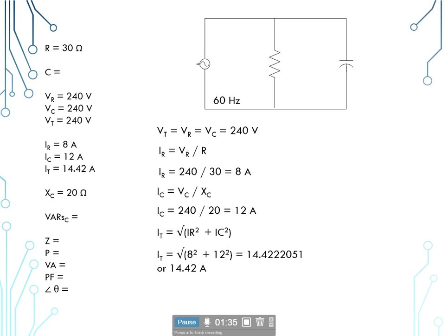amps. Again, you can see there if we tried to add them up, we'd have a total current of 20 amps. So that's why if we're not in a purely resistive circuit, our quick checks in our math do not work, so they're out the door.